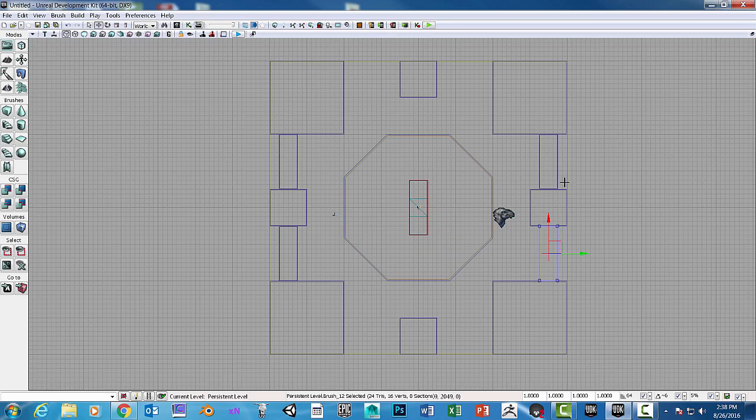There we go. And again, with this one, we're going to have to hold the Alt key, move it up to the center, right about there, and hit the space bar and then rotate to 90 degrees. So that'll be negative 90. Hit the space bar again until we get to the move. And there we go. And again, if we can center this to the center of the room, that'll keep everything aligned nicely. So I'm going to do an Alt. There we go with that one.